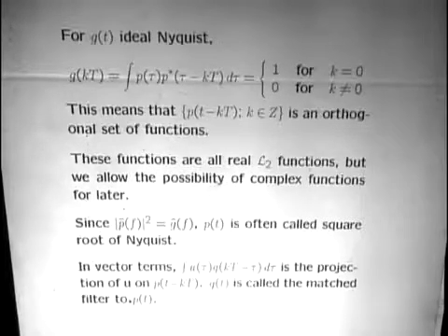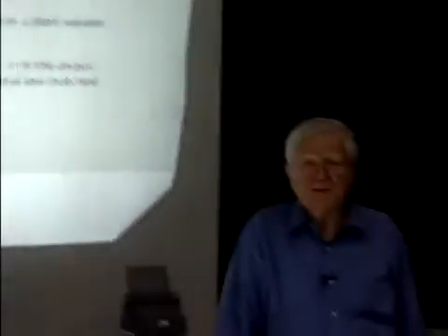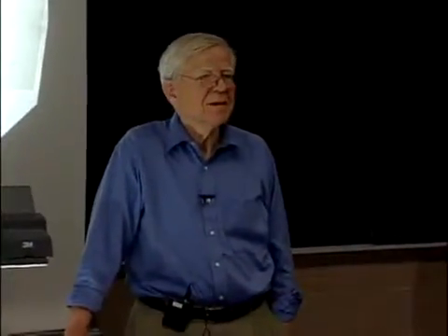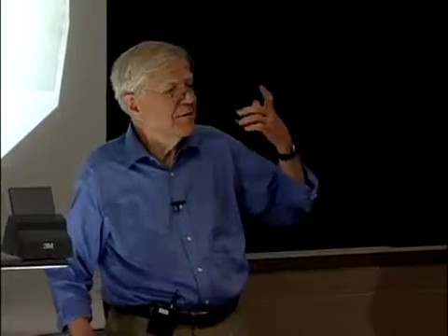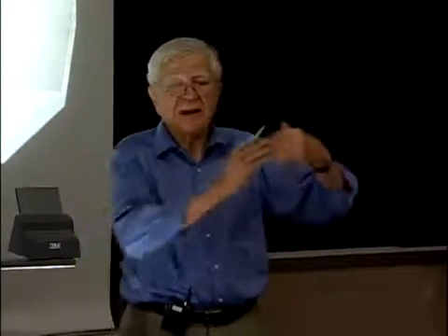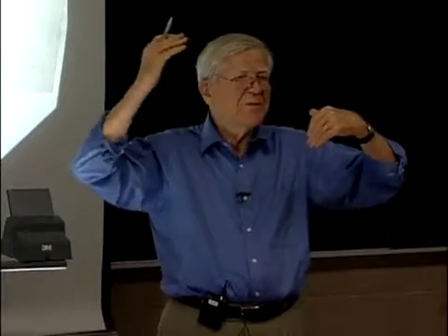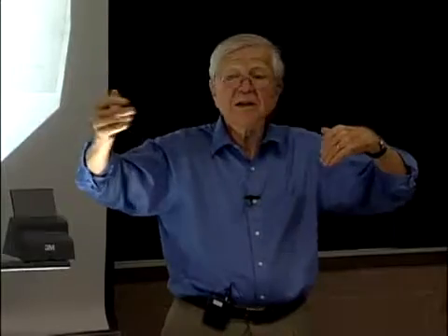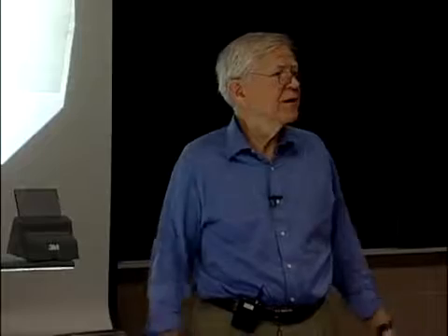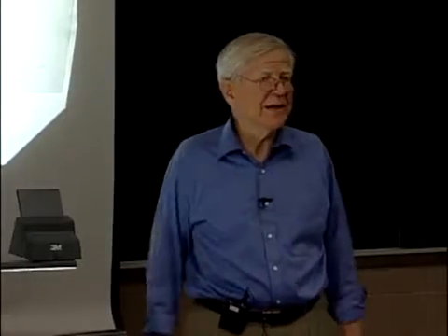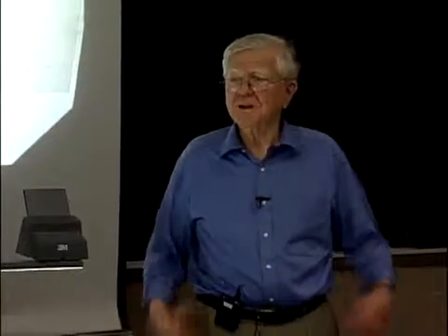Well, I've never seen anything in electromagnetics or in optics or anything else that lets me transmit an imaginary waveform. These are not physical. We will often think of baseband waveforms that are imaginary, real and imaginary complex, and when we translate them up to passband, we'll find something real. But the actual waveforms that get transmitted are always real. There's no way you can avoid that.